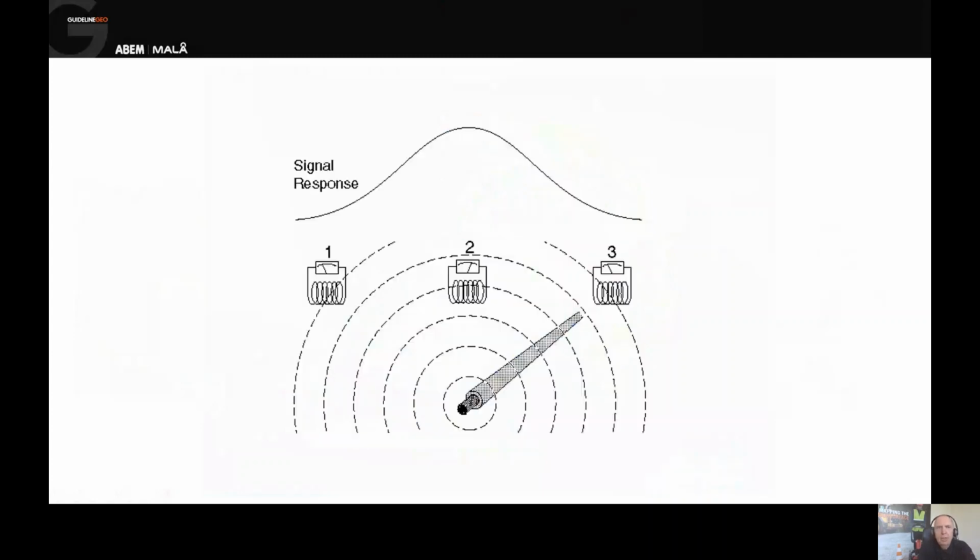But the point is here, what we're trying to do is we have in the receiver a coil, antenna or sets of antennas, different antennas, multiple antennas in there quite typically. We have an antenna, an aerial, and that is going to pick up that signal from underground. You can think of the pipe or cable acting like a big antenna from a radio station. That signal's traveling out through the ground, and we have a radio receiver on the surface. And in the basic principle here, that is what the receiver is for the EM locator. It's a radio receiver, and it's going to pick up that signal that's been generated.